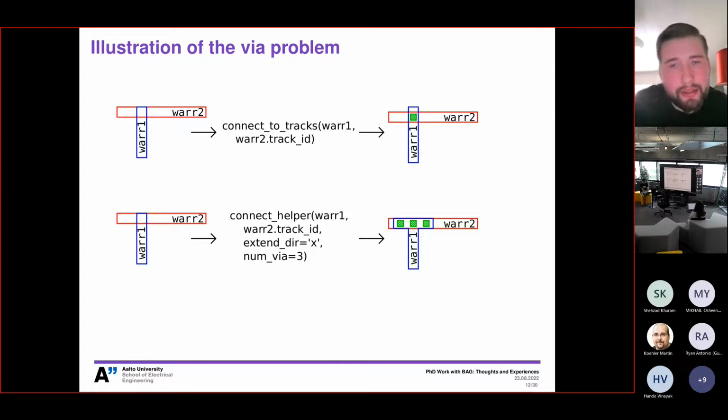You have to make sure that you don't short out when you extend into the X direction using a metal layer that is originally routed in the Y direction. So I don't know if that's a good fit into the original framework per se. You're saying it's too much of a hack to move back into the original? Yeah, maybe so. Of course, we could try to make a merge request to the original framework. Okay, thanks.